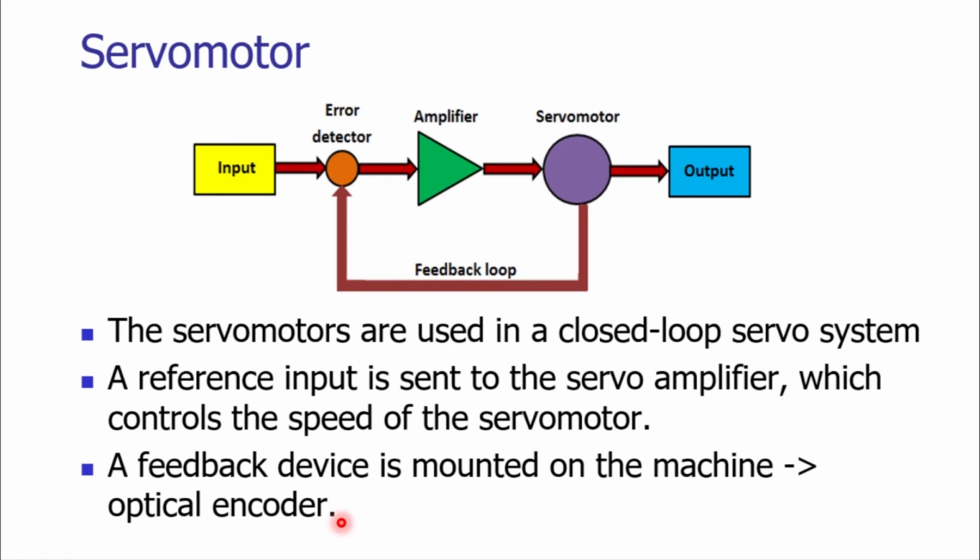As the light passes through the perforations, it senses and counts the number of pulses, and based on that number of pulses, we can easily find out the angular velocity of the perforated disc. If we mount the perforated disc and a set of phototransistors, then we can have continuous monitoring of the motor. That arrangement is provided on the servo motors.